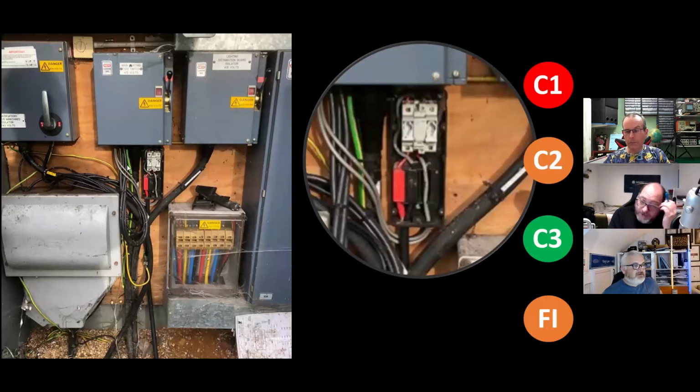Is this one of the pictures sent to you? Yeah. Even the bending radius and some of these cables going into the switch fuse, and aluminium conductor cables as well. I can't see any metering on it. Just looking at it, I don't understand how the DNO would even allow that to be connected. To be perfectly frank, but then again, one of the issues you'll find is there's a lot of installations where there are DNO intakes and there's no metering, because the DNOs still haven't got a proper record of everything they've got.